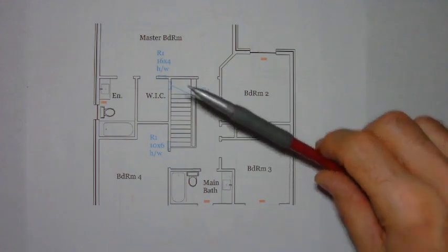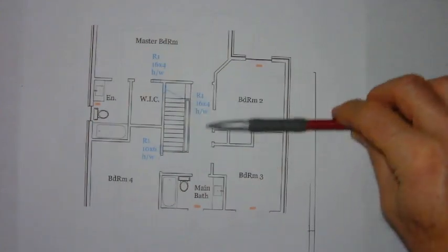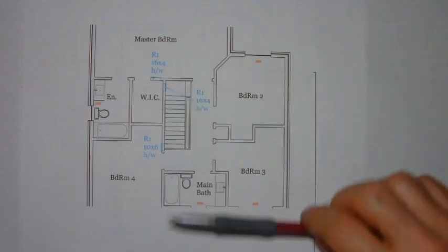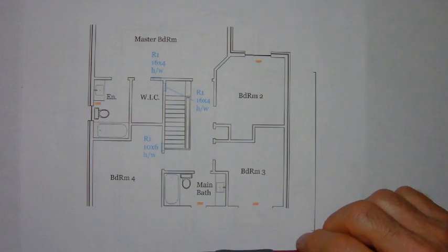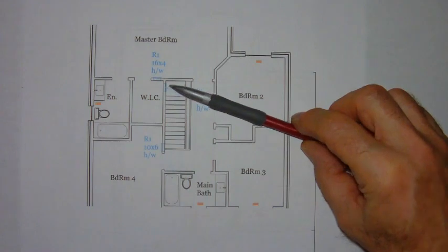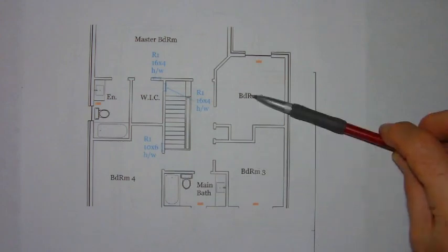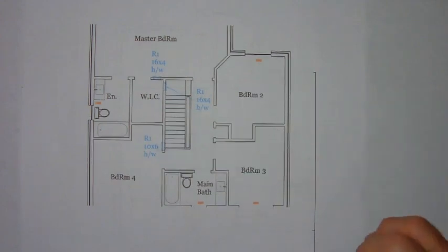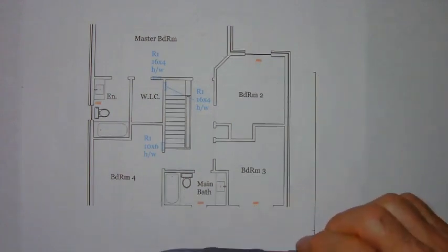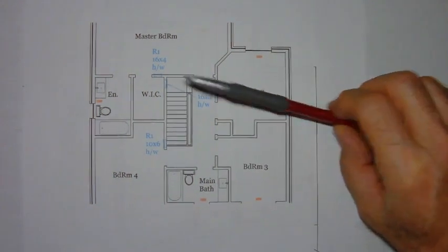Another rule is that at least one of the inlets must be centrally located, and a hallway is generally regarded as the central location for any floor, and so you'll be looking to place a return air in the hallway. Now, if you were planning to place a return air in each bedroom, then you are not required to put the return air in the hallway. But since we've got 4 bedrooms and the recommendation is for 3 return airs, then it would make sense to put 1 return air in the hallway.